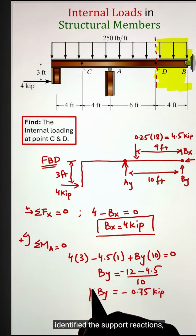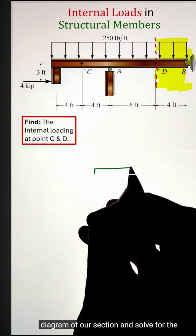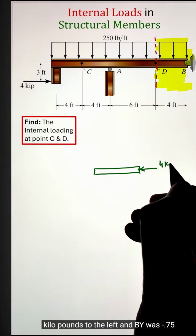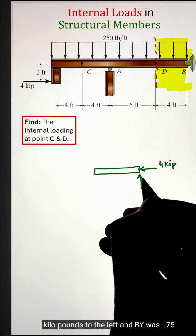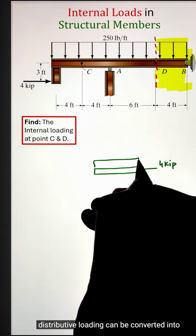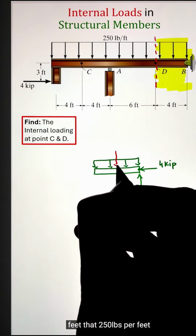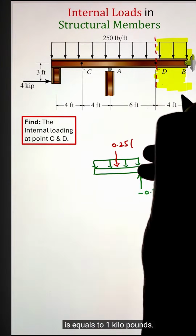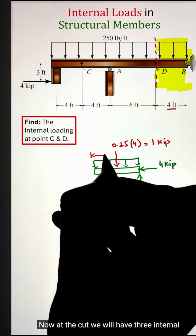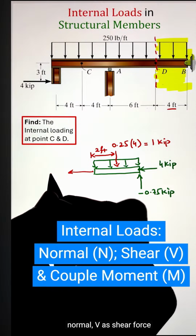Now, once we have identified the support reactions, let's go ahead and draw the free body diagram of our section and solve for the internal loads. Since Bx was 4 kilopounds to the left and By was negative 0.75 kilopounds going upward, now the distributed loading can be converted into a point load. Since we have a width of 4 feet, that 250 pounds per foot is equal to 1 kilopound.